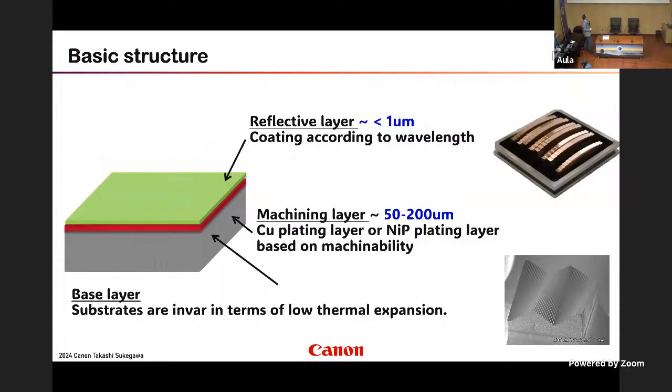And for other parts, when there is no requirement from the end customer, we ship this kind of structure like that. This is the DKIST IFU multi-faceted mirror. This is a 112 monolithic integrated mirror. But what kind of structure are we providing? Usually the base material, almost 99%, as substrate is Invar. This is a metal with low thermal expansion.